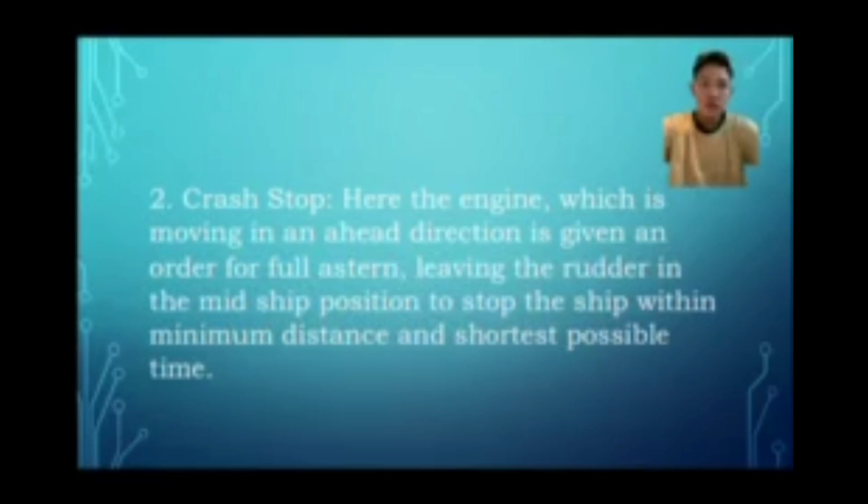Next is crash stop. Here the engine, which is moving in an ahead direction, is given an order for full astern, leaving the rudder in the midship position to stop the ship within minimum distance in the shortest possible time.